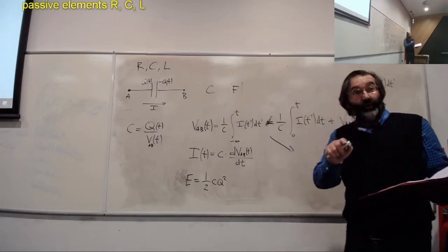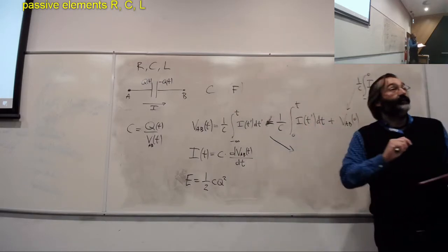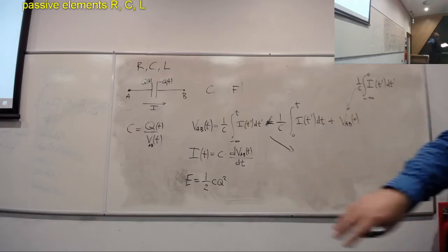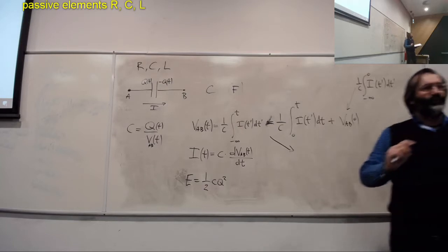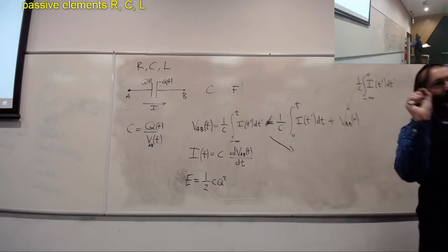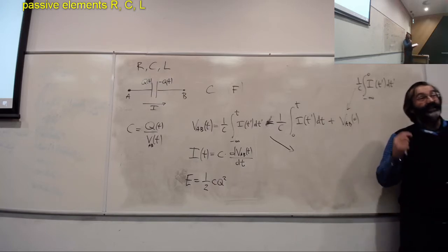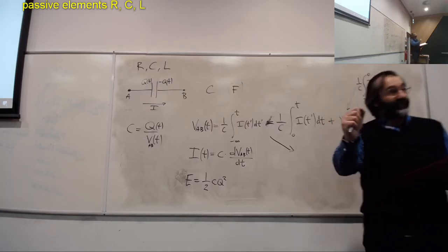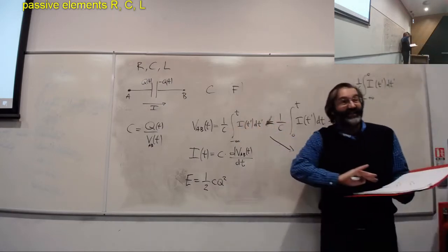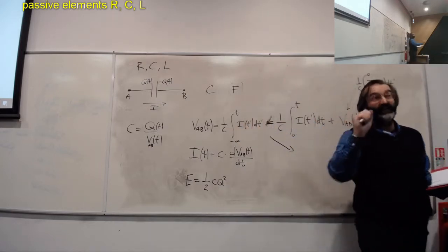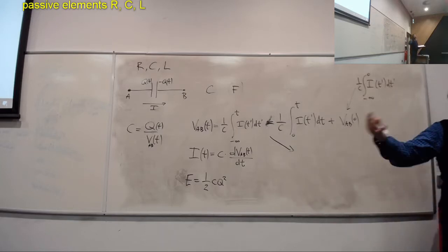This means, though, that it allows sudden changes of the current. We will demonstrate this in a moment, looking at the RC transients, probably something you've obviously done, but we will point out this thing. So this means that the capacitor is an element that is capable of giving bursts of current. It cannot give sudden changes in voltage, but it can give bursts in current. And this is used technologically.